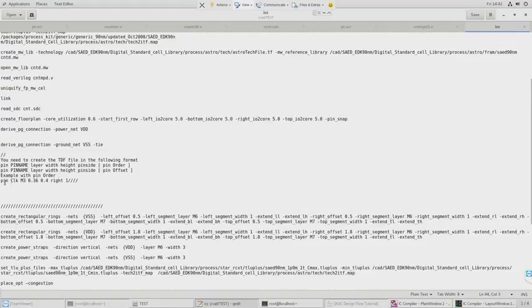So here is the pin name, then the pin, then the pin name with which metal layer you want to connect, along with the height and the width, and at which side it will be placed, whether that is right or left or up or bottom, you have to mention along with the order. That means whether it will be 1, 2, 3, or 4.